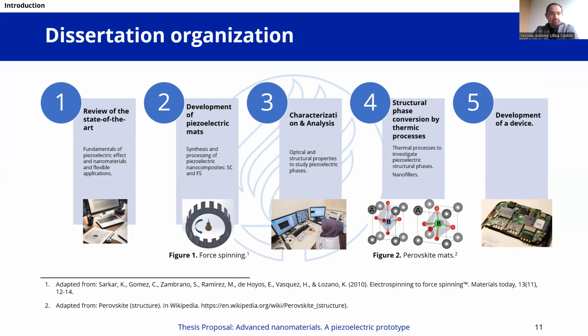Stage number 2 is the synthesis or development of these piezoelectric materials, maybe by spin coating or electrospinning processes. In stage number 3, we want to do the characterization and analysis, which is the optical and structural, to understand the optical and structural properties and to study the piezoelectric phases.